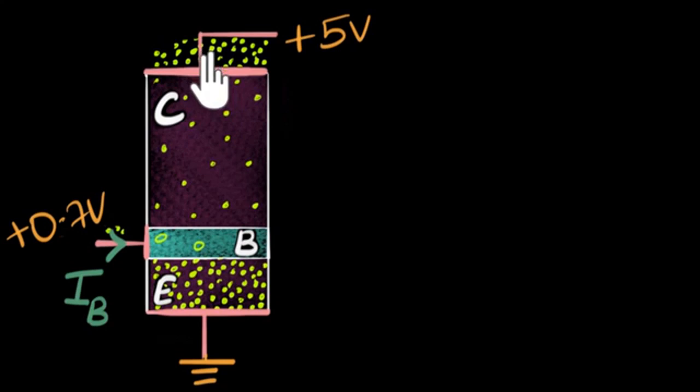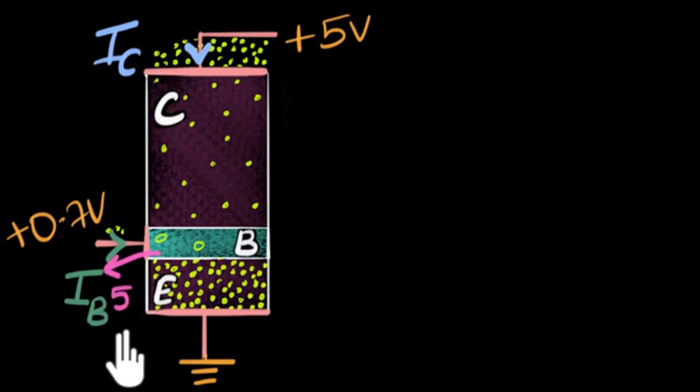Similarly over here, notice because of the electrons coming out from here, we get a current downwards. You see that? Electrons are going upwards, so the conventional direction of the current is downwards. So we get a current downwards, and we call that current the collector current. This is the collector current. And now if you put some numbers, let's say about 5 electrons came out from here, and let's say about 95 electrons came out from here, from this wire.